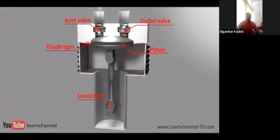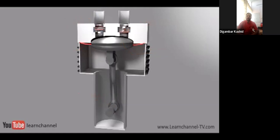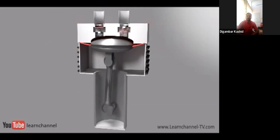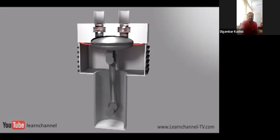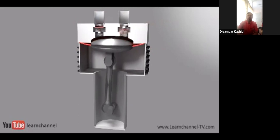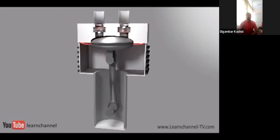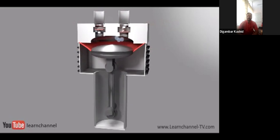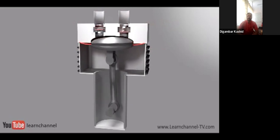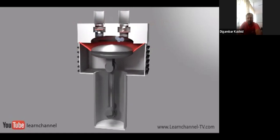The diaphragm compressor belongs to the family of the piston compressors. Here, the suction chamber is sealed from the piston by a diaphragm. As an advantage, the compressed air in the compression chamber does not come in contact with the lubricated piston, and thus can be kept free of oil. The weak point of a diaphragm compressor, in general, is its membrane itself, since the elasticity is limited. You would use the diaphragm compressor, for example, in the food industry or to fill divers' bottles.